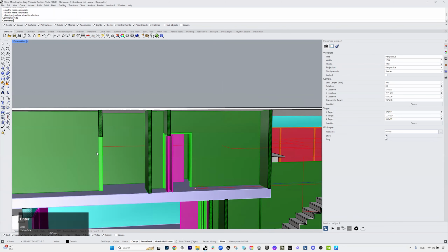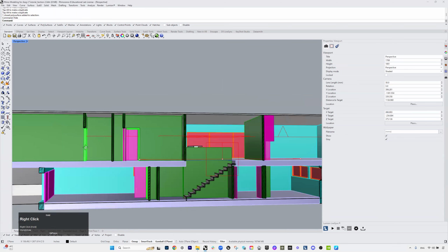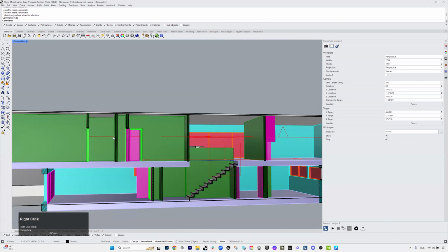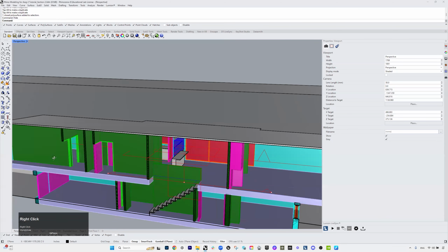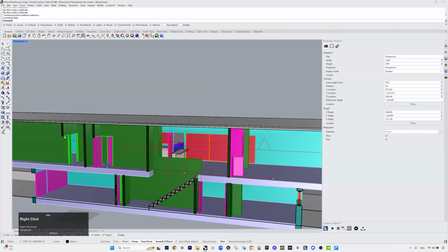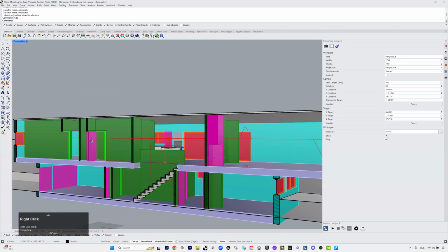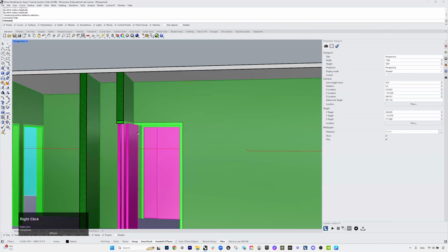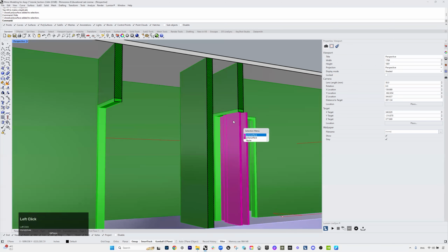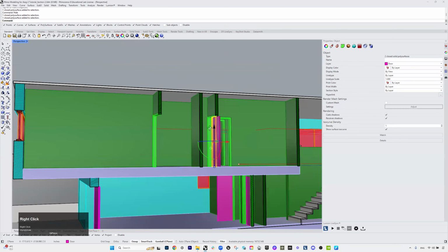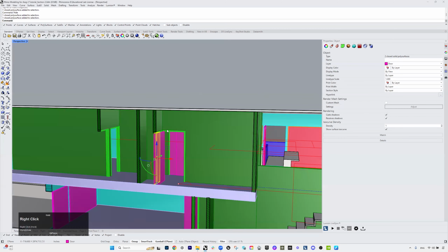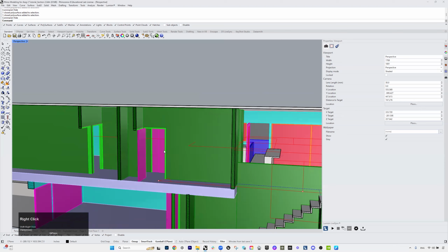So I'm going to hide this door, and you just look through the frame. That's how we want to show the doors in a situation like this. It's the same thing over here. These are the sliding doors to this closet, which I'm cutting through with the clipping planes. So I'm going to hide that as well.